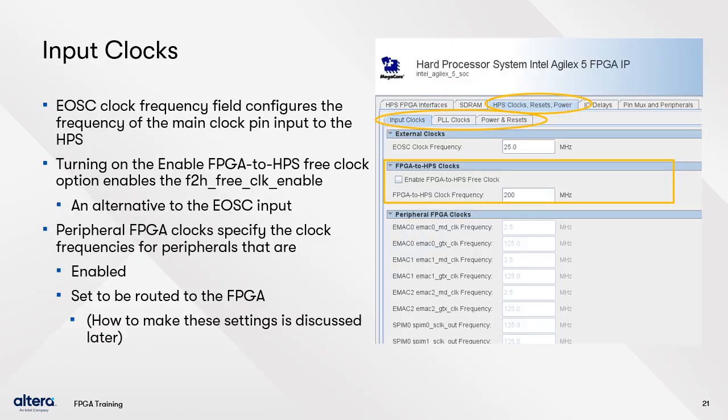This group of tabs is for setup for input clocks, internal clocks, and output clocks, and resets. Some of the configurations for this section are added into these files as needed: the SDC file generated by Platform Designer, and the handoff binary for the FSBL. This tab contains the configuration for the external clocks, FPGA to HPS clocks, and peripheral clocks.